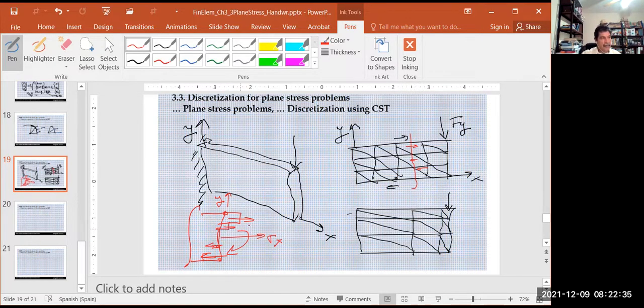Also, you can integrate this and add the four forces, and the value of that should be 0. Because if you make a cut here, you see that I have a vertical force downwards. So in this cut, there should be no net axial force. So these two must be equal to those two and cancel to 0. They are not precisely equal to 0 because this is just an approximation, but it should be 0.